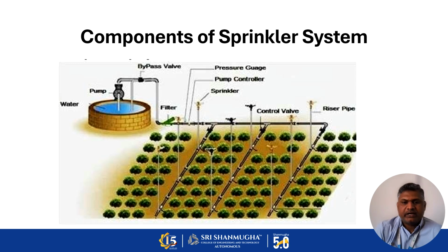These are all like drip irrigation. At the end of the main pipes, we fix flush valves to release the flushes in the system. This type of sprinkler irrigation is mainly used for close growing crops such as groundnut, sesame, forage crops, and some flower crops.